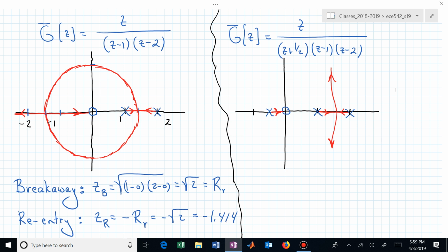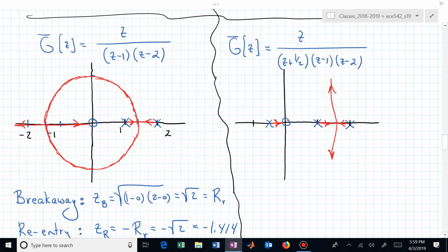What about the next root locus on the right side of this graphic or of this screen? Now we have more poles and zeros. We have 3 poles and a 0. And a lot of the behavior that we will be determining with these root locus, a lot of the big behavior will be determined by the pole zero excess. How many more poles do we have than zeros, finite zeros? And here we have 3 poles and a 0, so the pole zero excess is 2.